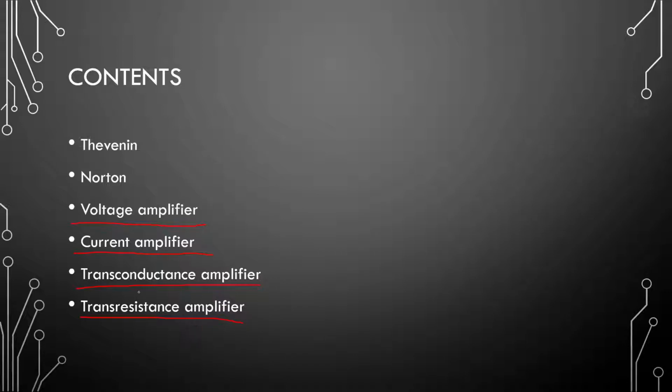Transconductance you should have heard of when we were doing common emitter amplifiers and such. That is because it is a transconductance amplifier, not really a voltage amplifier, which we convert to a voltage amplifier by placing in the collector resistor. So you can convert amplifiers from one form to another by adding a resistance or something. So that can be done.